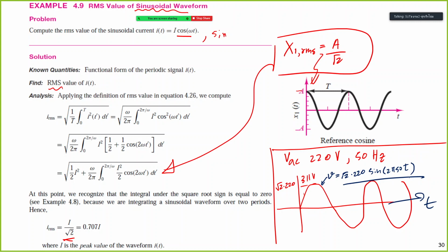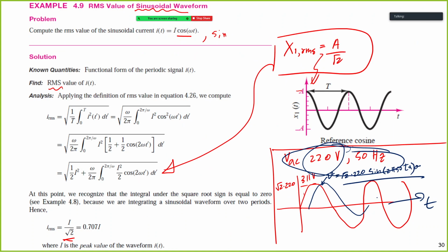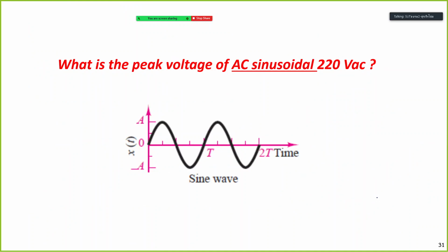But when we make a calculation, usually we just use the RMS value 220 volt, and with the phase shift, if you have a phase shift, you add it here. The phase shift makes the vector have some angle from the reference axis.